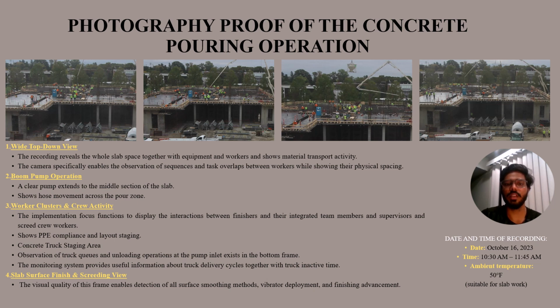We also captured the truck staging area, which helped us analyze the delivery cycle and idle time, like when the concrete is being poured on a site and kept for use after an hour or 1.5 hours. And lastly, talking about the slab surface and finishing, the vibration was performed, helping evaluate the quality and smoothness of the concrete finish, so that there are no air pockets remaining on the slab.